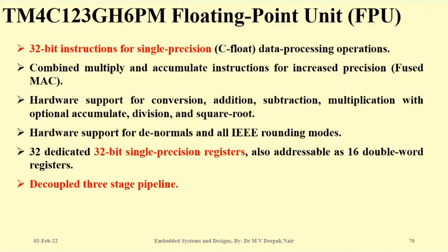without using a decimal point there? It is not that you will have 0x3F.2ACD. No, it is not allowed in the memory. We don't have a special character like a dot in the memory. So all the data which will be loaded will be a normal number like 32FABCD, something like that, in hexadecimal. It will not have a dot in the memory.